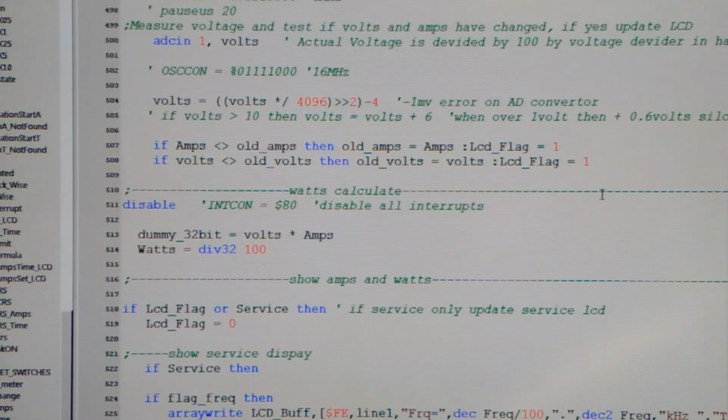What this flag means, when it comes to talking I2C to the LCD screen, is I'm allowing it to rewrite the LCD screen to display the new number. Now, I have seen a lot of sketches getting back. I'm taking long to explain this. So, if the value has not changed, why are you going to write on your LCD? You shouldn't do that. Why is that?